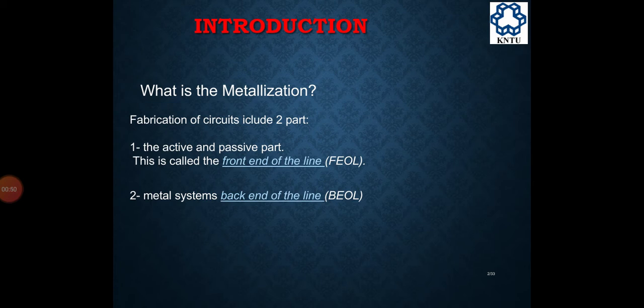There are other uses of metallization, such as to produce metallized areas called bonding pads around the periphery of the chips, to produce metallized area for the bonding of wire leads from the package to the chips.